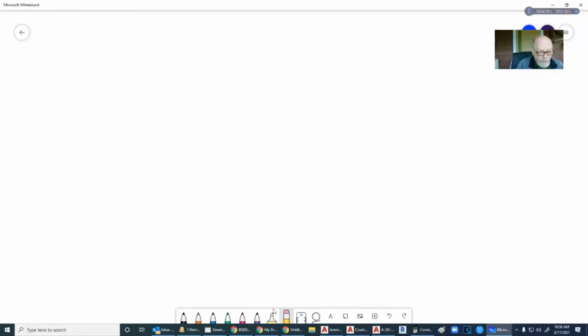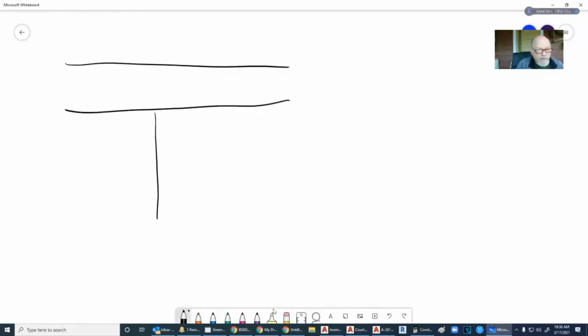The other day we got into the T's in old school. We have the through wall, we've got the intersecting wall. We would have a stud in here that's going to be on the intersecting wall. And just as, like I say, old school, then we would have this T in there. And this one here could be a full stud, or it could be blocking. Most of the time it was a full stud.